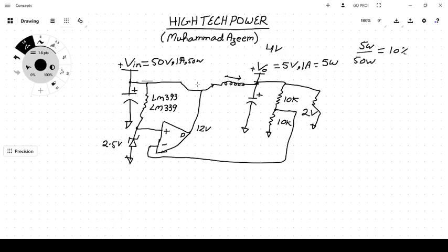But at the moment the transistor is off, and the current was lagging, so the end result is that the inductor will start increasing the voltage across it, so that increased voltage would be reflected to the whole path, and the voltage would start to increase across the transistor as well, and that increased voltage would be such a high value that it will destroy the transistor.